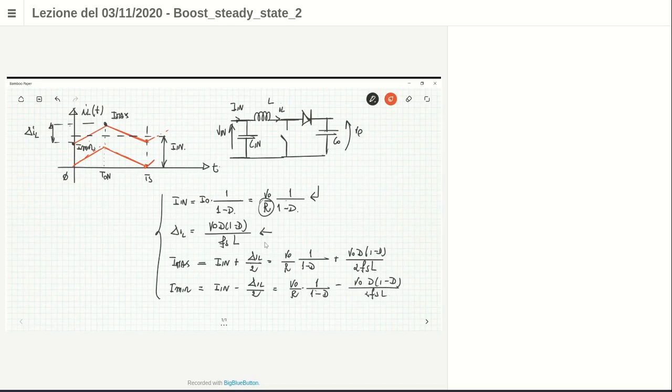It is the minimum possible current flowing through an inductor that makes it possible to define the operation of the boost as in CCM. Basically, this is also called the boundary conduction mode, the critical mode. If you increase the load resistance R above this value, then the current goes negative.